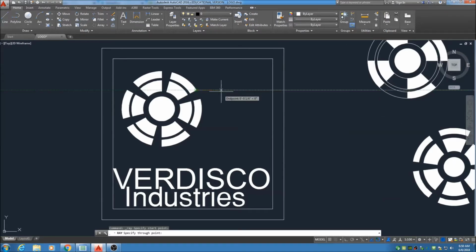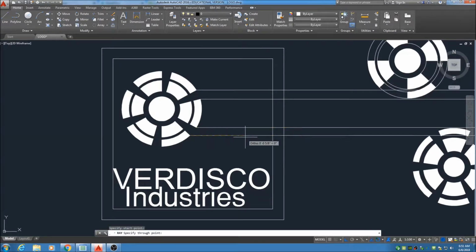Now, again, I want nice straight lines, so F8. That is going to turn on our ortho. Click once, click twice. To get out of the command, you hit the space bar. To bring the line back, click once. Make it again. Then you can see you could work a little bit faster this way.